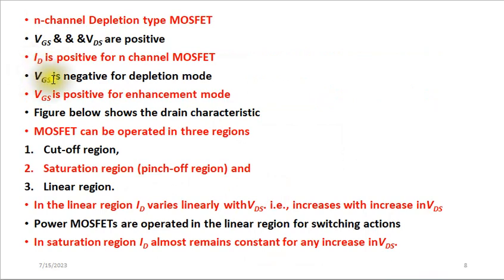But the VGS should be negative for the depletion mode. If you want to operate it in depletion mode, that is to reduce the concentration of electrons in the channel, you use negative VGS.